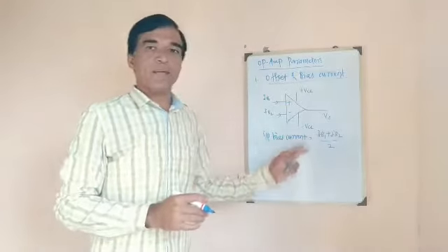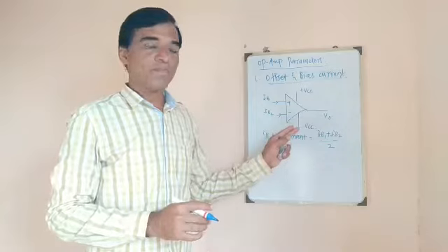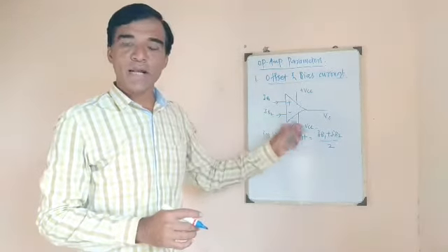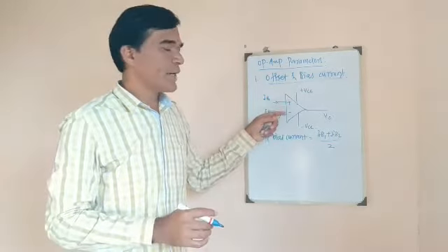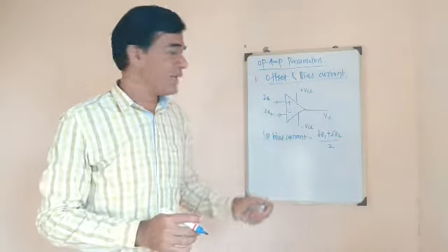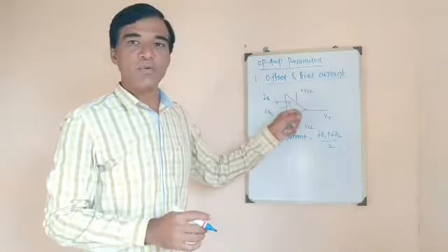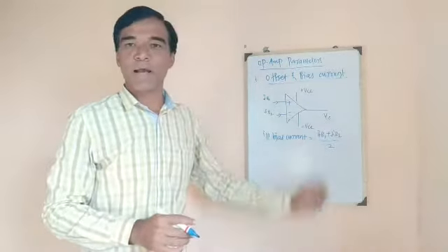When we apply the biasing voltage to the op-amp, IB1 and IB2 are the currents which are flowing inside the op-amp through the non-inverting and inverting terminal respectively. The average of these currents entering into the op-amp is known as input bias current.